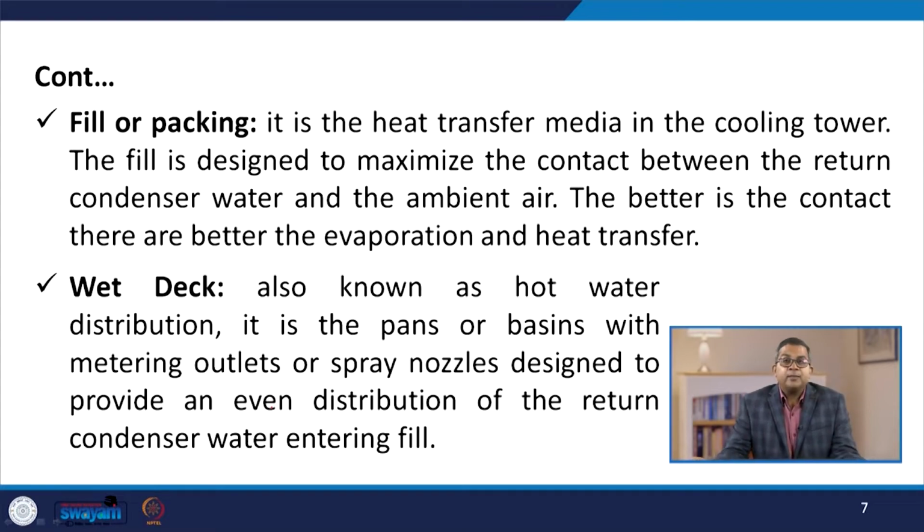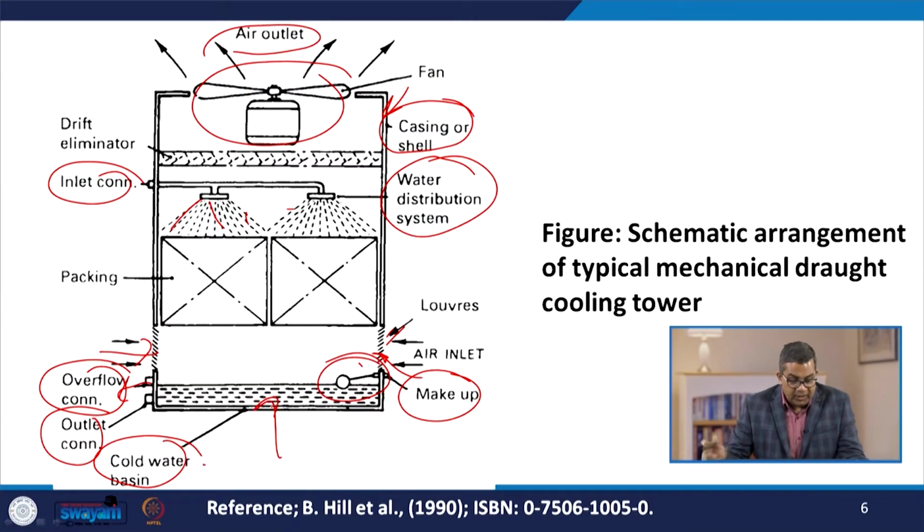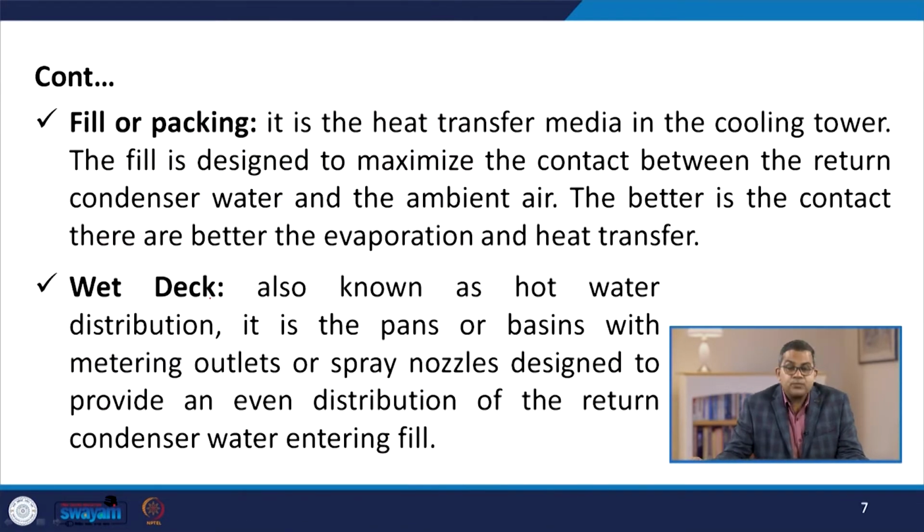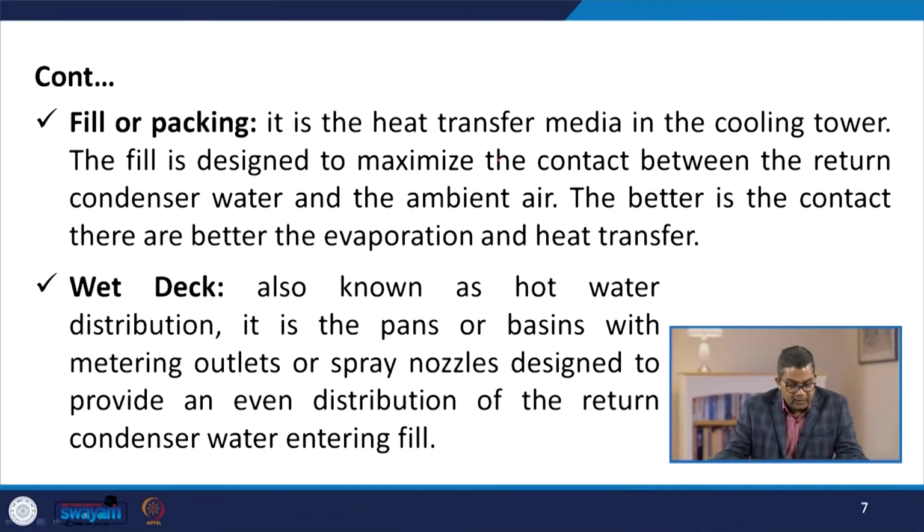Because we are discussing the elements of a cooling tower, as you recall, we have some packing over here. This fill or packing is the heat transfer media in the cooling tower, and these fills are designed to maximize the contact between the return condenser water and the ambient air. The better the contact, the better the evaporation and the heat transfer. Then there is a wet deck. You see that here we have this wet deck. This is also known as the hot water distribution.